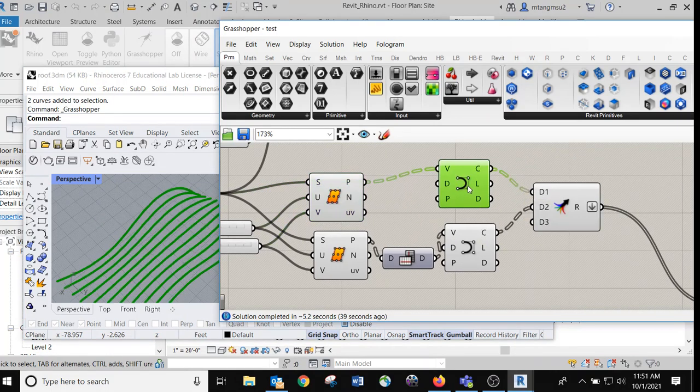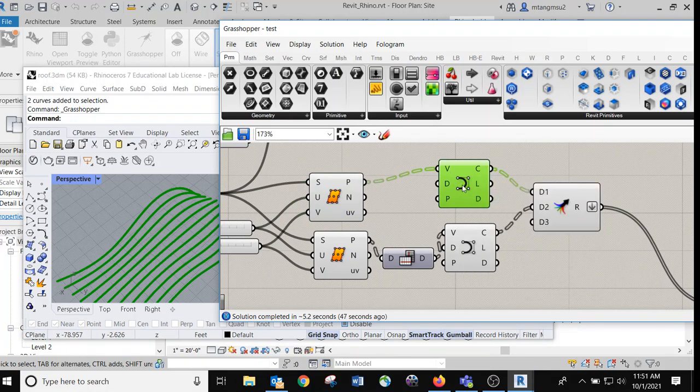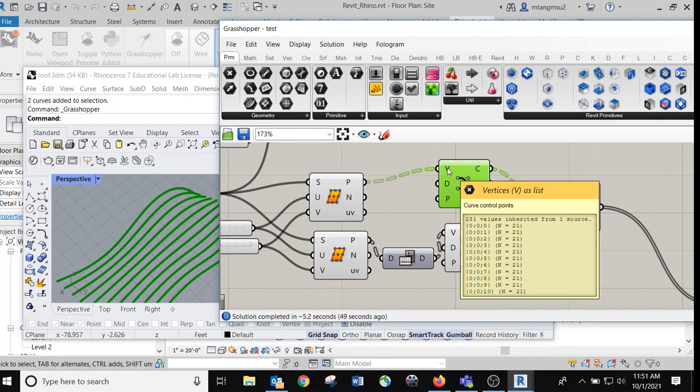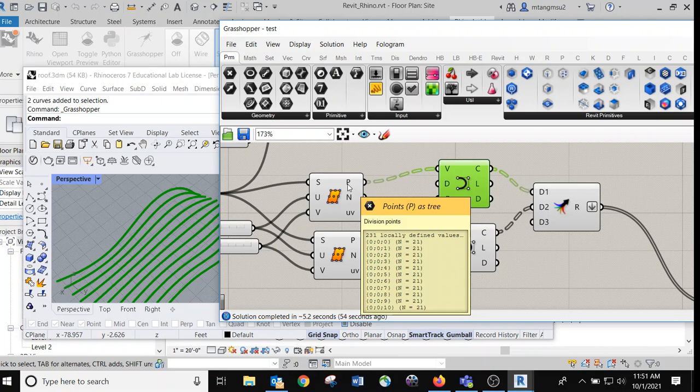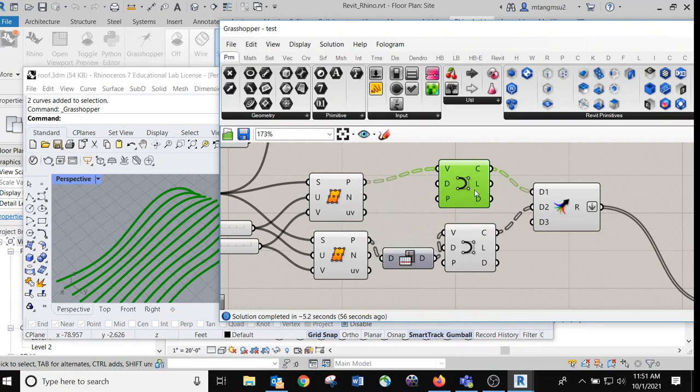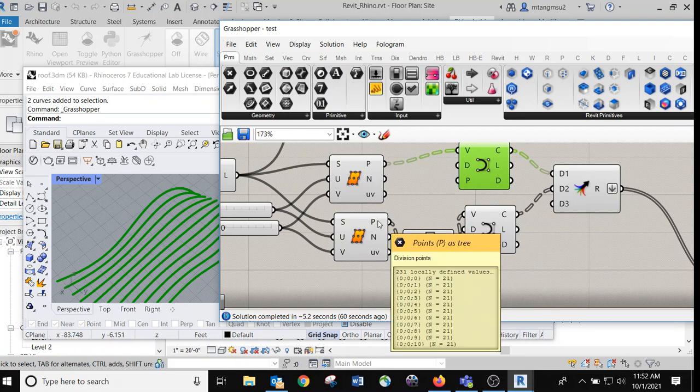Then I will create a curve based on these points, right? So this is basically feeding vertices, and then you create a curve based on the vertices. Because the data structure coming out of these points is organized based on U and V, the first group of lines follow the U direction. So you have all the lines here. And in the second branch, I rotate, what we call flip matrix. You basically flip the data structure. It's kind of like going from vertical to horizontal.